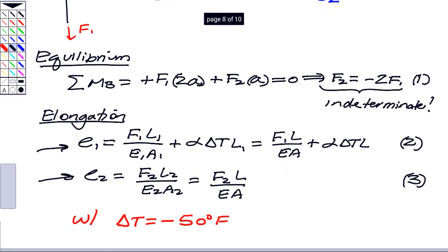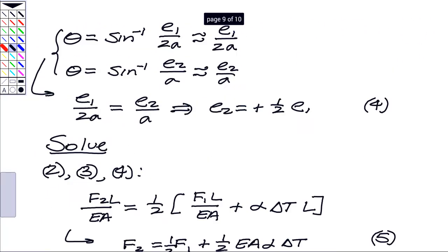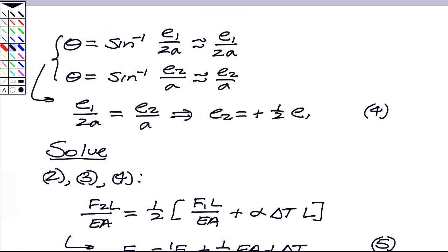And finally, I need to then say what the relationship is going to be between E1 and E2. Again, abiding by the sign conventions that I have, you can see here that the relationship between E1 and E2 is going to be a plus sign just based on the kinematics. That gave me all the equations that I need. I solved them simultaneously in order to get the loads carried by these segments, and then from that I can find stress. I can also calculate the shear force and bending moment through the cut through that L-shaped bar.